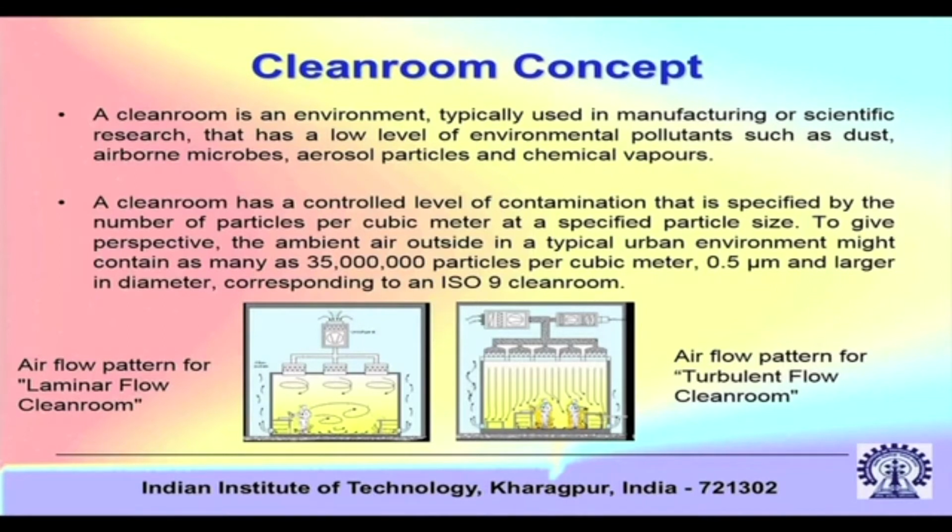So a clean room has a controlled level of contamination that is specified by the number of particles per cubic meter at a specified particle size. Typically, ambient air outside in a typical urban environment might contain as many as 10 to the power 6 particles per cubic meter, and in the busy urban places that are there in India, it might be even more, I do not know, of 0.5 micron and larger in diameter, corresponding to an ISO 9 clean room.